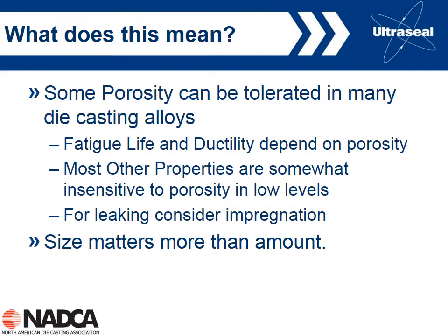We need to design to accommodate the porosity, but maybe we don't need to go to great lengths to eliminate it just because we don't like it. Don't spend a lot of money on trying to totally get rid of it if it's not a problem. If we are concerned about porosity, maybe we should consider impregnation. Impregnation materials are available that will certainly outlive all the conditions that the casting is likely to see in service.